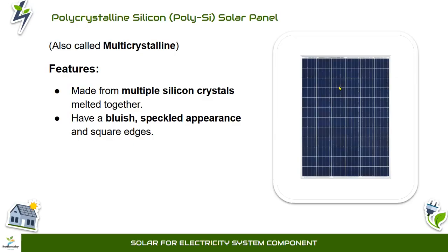It's still like more like shining. Okay, that is how, by merely looking at a poly panel, you should be able to identify them with this identity. They are bluish in color and they sparkle in appearance. So when it comes to efficiency, it's moderate, 15 to 18%. It tells you that mono panel is more efficient than poly.